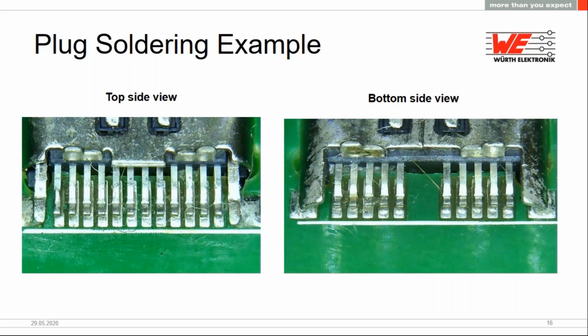Similar to the receptacle, it is also very important that we solder the plug connector very carefully. Now, if you see the top side and the bottom side view, the pins are again laid out very close to each other, and we just don't want to create an accidental short just by putting on too much solder and getting it mixed with the adjacent pin. Or we don't even want to put very little solder and leave one pin hanging, which would just create a loose connection.